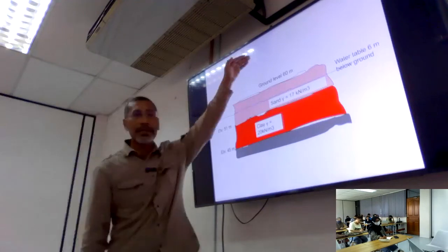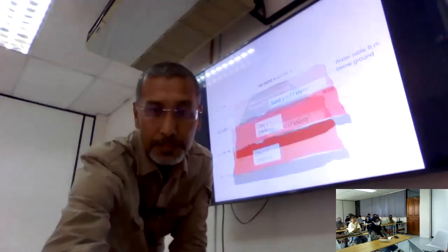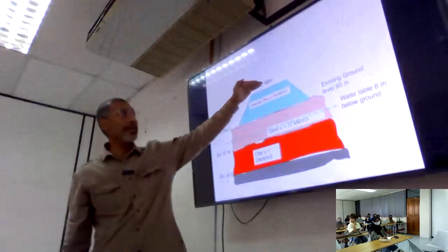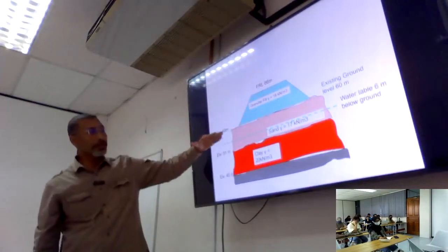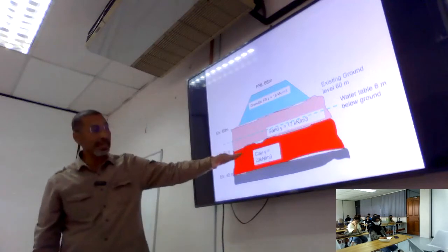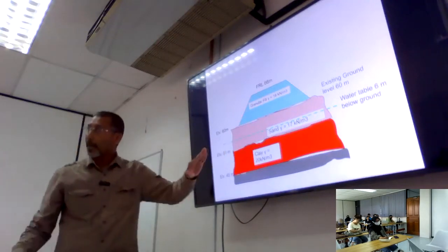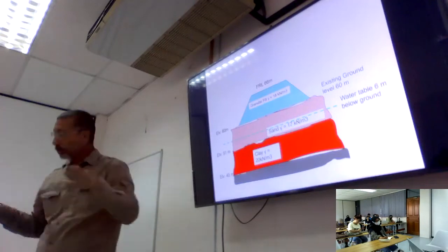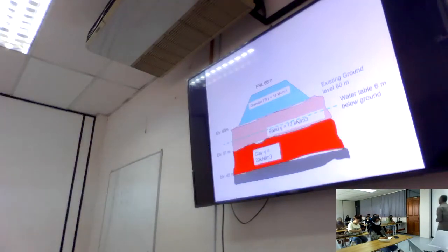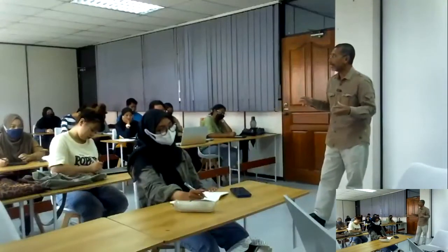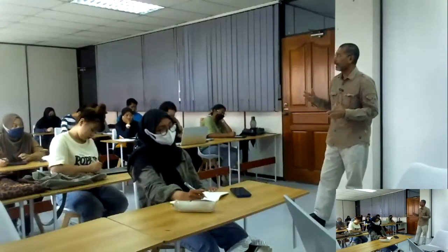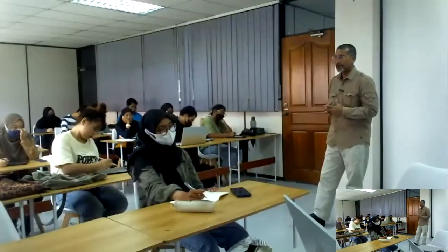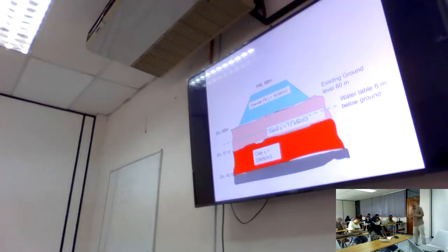What will happen is that once you have your highway up here, you need embankment, right? It will cause this clay, especially this clay layer, to settle in the long run, because clay, like I mentioned before, will take time to release whatever water is inside it if there is heavy loading on top of it.